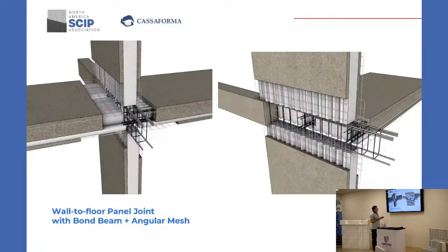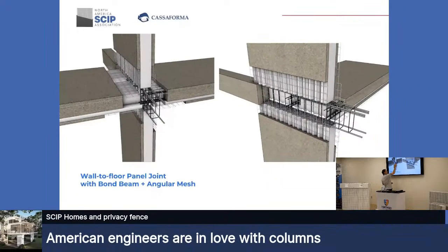The only thing that is important to see here is that the live and the dead loads come here from the mortar. If I have just foam here, the load will have to be distributed through the compression layer that we have there. So in order to avoid that, usually this area is out of concrete.